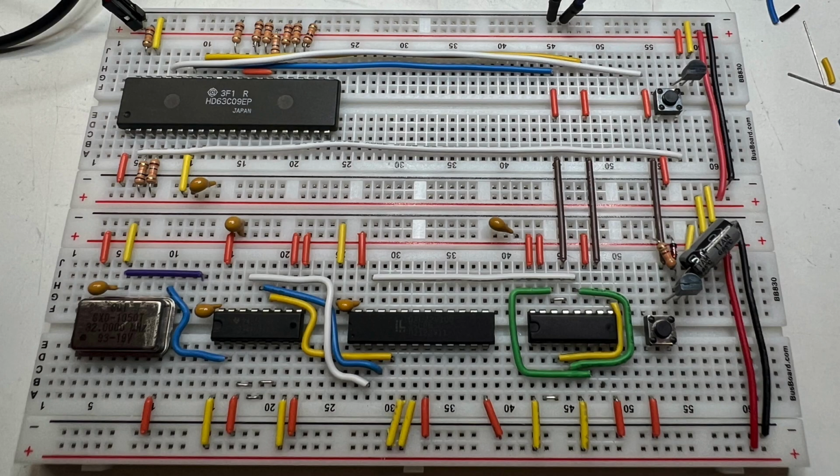So here's what we have so far. Here's the NMI circuit up there. And now the CPU should be all ready to run some code. A NOP is hard-coded on the data bus, and we can reset the CPU properly. So what we should see is the address bus counting upwards as it increments the program counter and fetches NOPs forever.